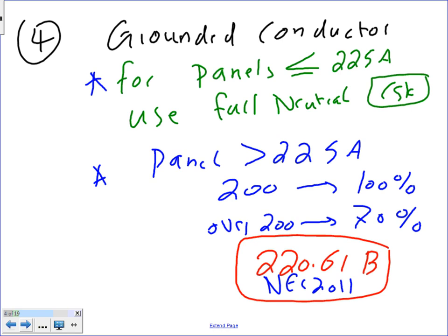Okay, so with this, the grounding conductor. In a case like this, everybody knows what my size is going to be then. I'm going to use blue. My size is going to be 1 conductor, because let's just say my overcurrent protection device was 200, right?